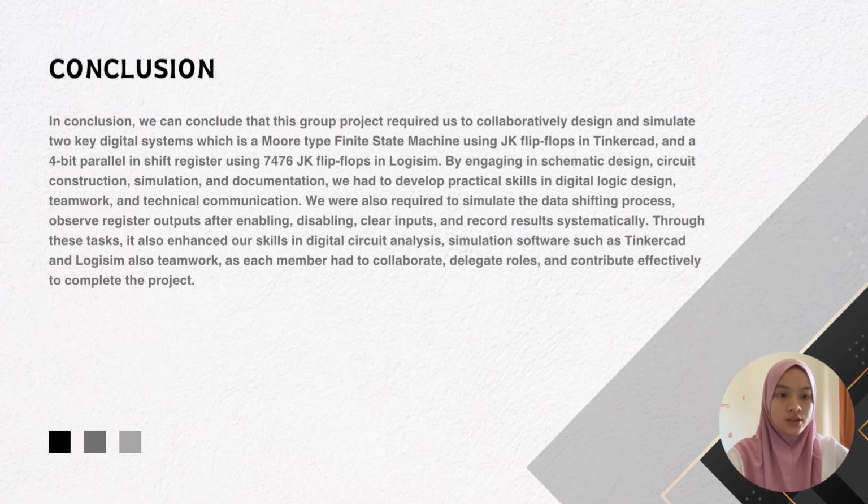In conclusion, we can conclude that this project required us to collaboratively design and simulate 2 key digital systems, which is a multi-type finite state machine. The first task used JK flip-flops in Tinkercad, and the second task is a 4-bit parallel-in shift register using 7476 JK flip-flops in Logisim. By engaging in schematic design, circuit construction, simulation and documentation, we developed practical skills in digital logic design, teamwork and technical communication.